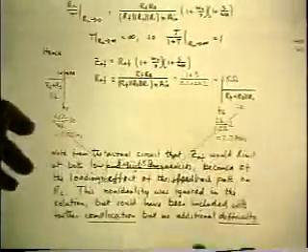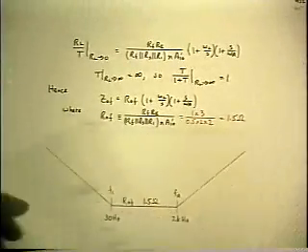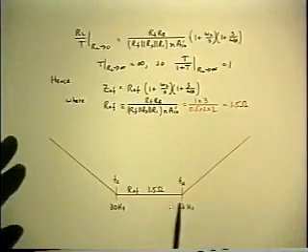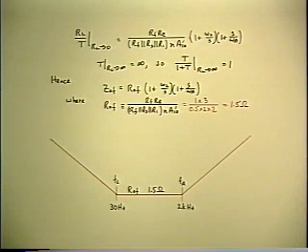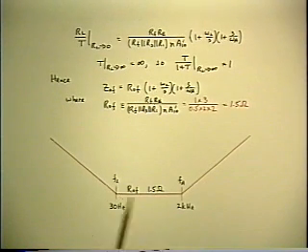Okay, now another comment about the output impedance. It's very low, but only over a pretty narrow range, which means the damping factor for the loudspeaker, which is part of the design criteria, is not so good when you start getting outside that range.